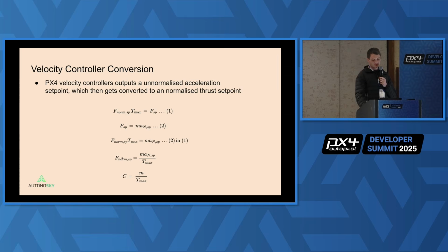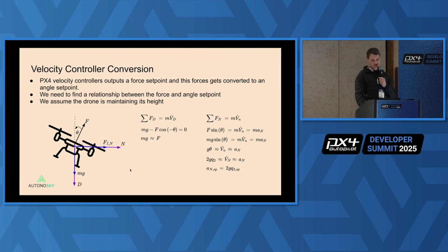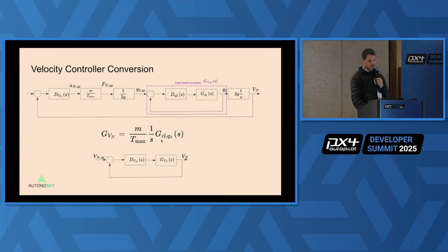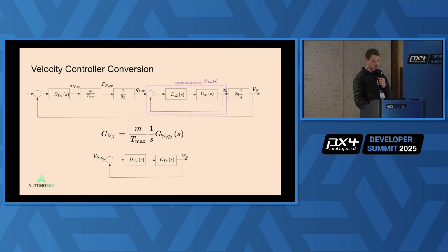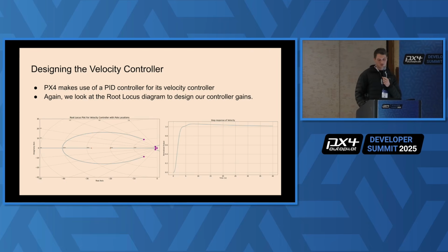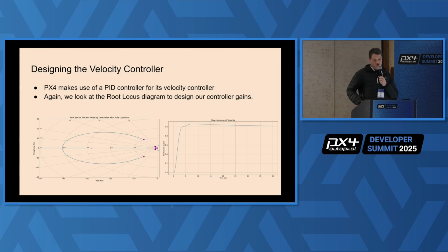We then substitute these conversions into our controller block diagram, and then we can simplify, and then we find the model on which our velocity controllers will control on. And then we just apply the same procedure where we design the velocity controllers in whatever control technique you want.